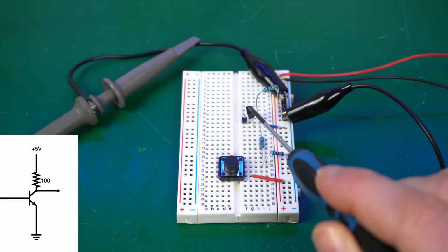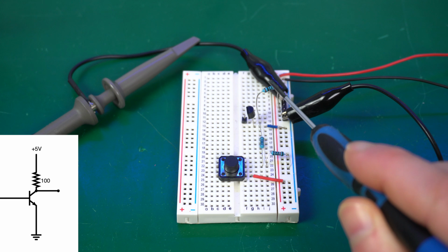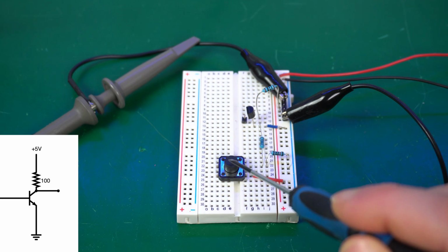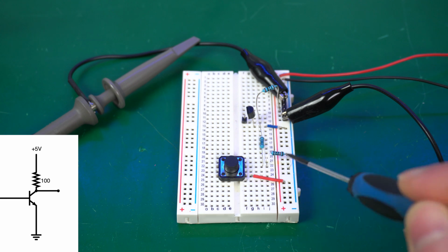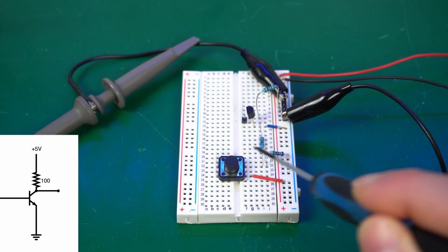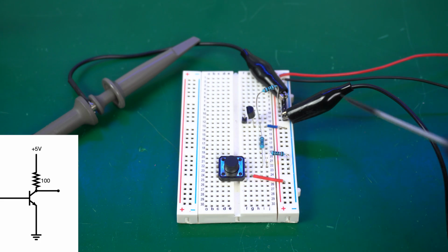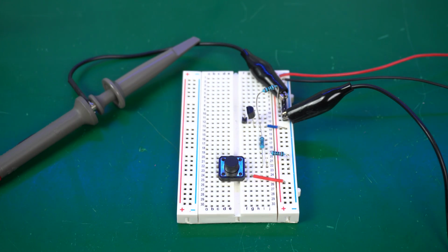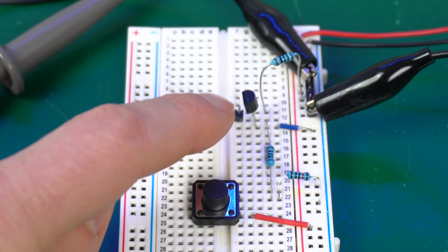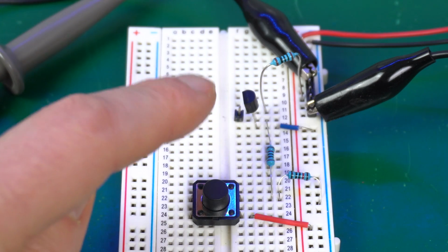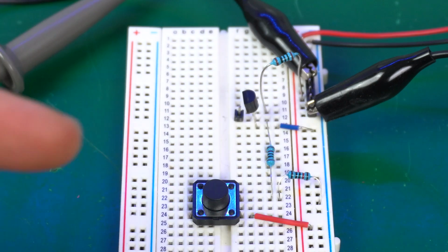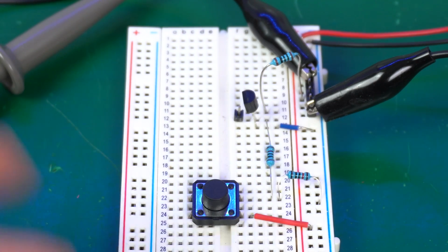Here we have a transistor set up in a very similar way to the Amstrad. We have a 100 ohm resistor at the collector and the emitter is tied to ground. And the base itself is connected to this button. When the button is not pressed, there are 0 volts at the base, and when we press the button, we give it 5 volts. So the button will be kind of our clock signal with the advantage that we get to control it to see what's going on. The specific transistor we have here is the BC547, which is a very common and easily available NPN transistor. I would love to be able to use this to replace the weird one on the Amstrad board.